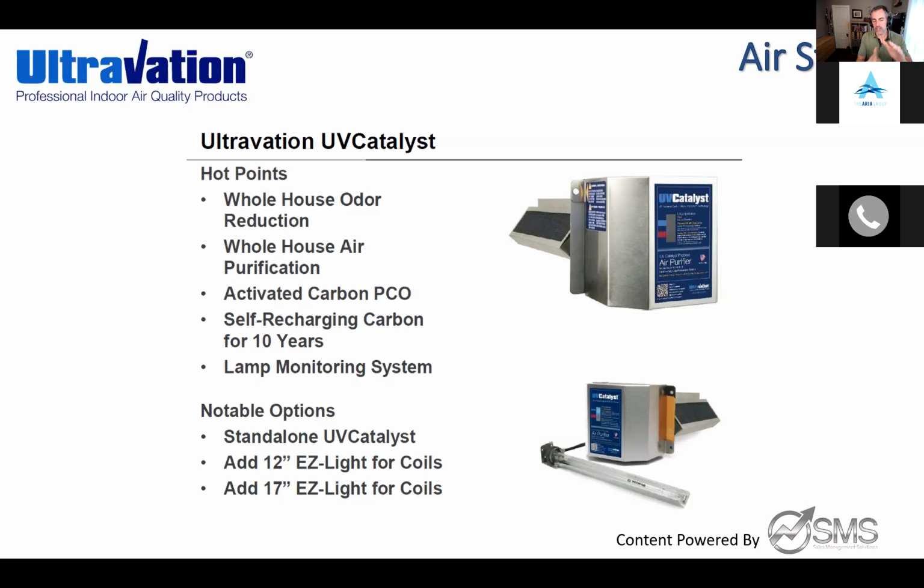But here's the thing: because of the PCO, photocatalytic oxidation, I don't care what company makes it, there is a slight ozone byproduct from that reaction process. Now, the percentage or chance of the population being sensitive to ozone is very minimal. But there is that random person who is. My own contractor noticed the PCO reaction just standing in my basement working on my system. He's my wife's best friend's husband. It was like, oh wow, after all these years, I still hadn't met anybody until he noticed that ozone-y smell.